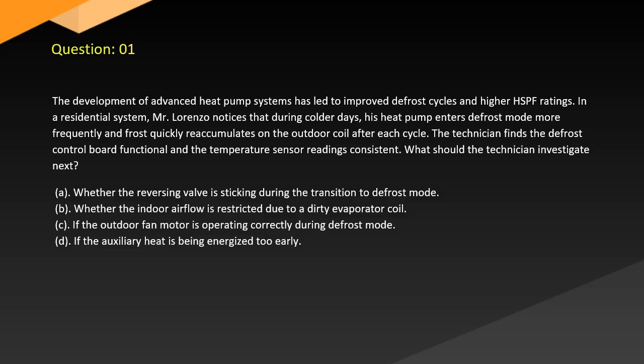A. Whether the reversing valve is sticking during the transition to defrost mode. B. Whether the indoor airflow is restricted due to a dirty evaporator coil. C. If the outdoor fan motor is operating correctly during defrost mode. D. If the auxiliary heat is being energized too early.